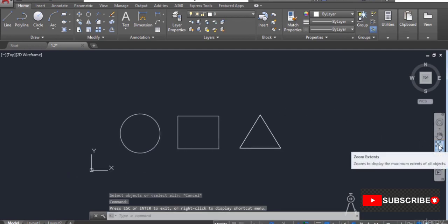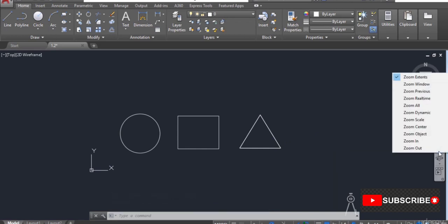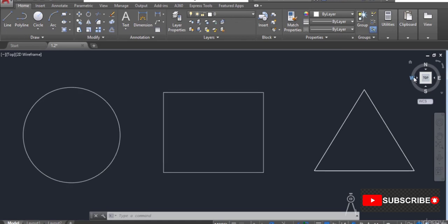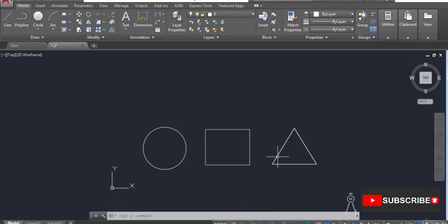In order to use the zoom tools, simply select this small arrow right under the zoom extents tool, and we have multiple options for zoom. You can select any of these options. For example, in this case, zoom extents is selected as default. If you select zoom extents, the drawing will fit completely in the area provided. So wherever our drawing is, it hardly matters. When you select zoom extents, it will fit in the provided space.